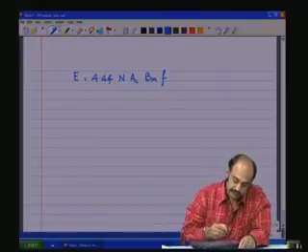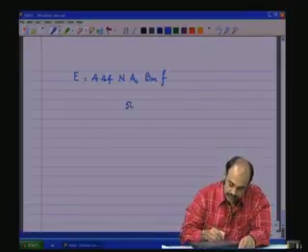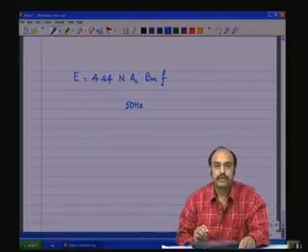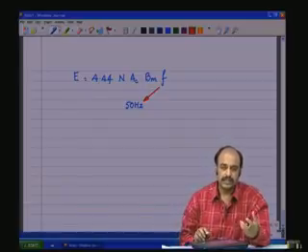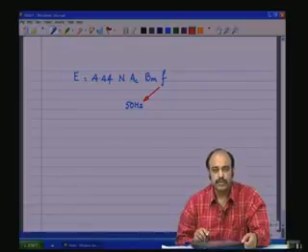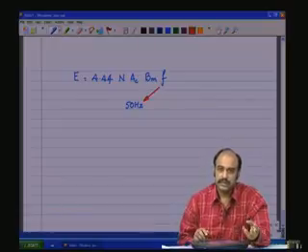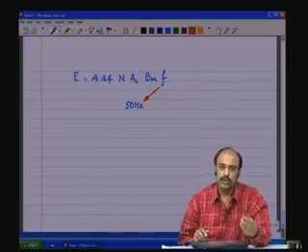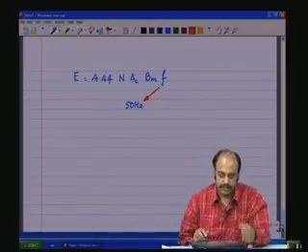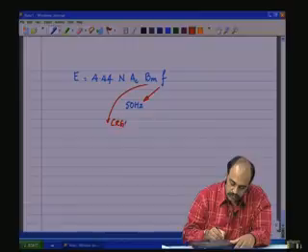Now, here, for our mains, which is 50 hertz, the most common types of core materials in the market, especially for the 50 hertz frequency, are CRGO, which is the cold rolled grain oriented, or CRNGO, the cold rolled non grain oriented, which is slightly less expensive. So, if we are using, let us say, CRGO, this would be around 1 Tesla as the design value.